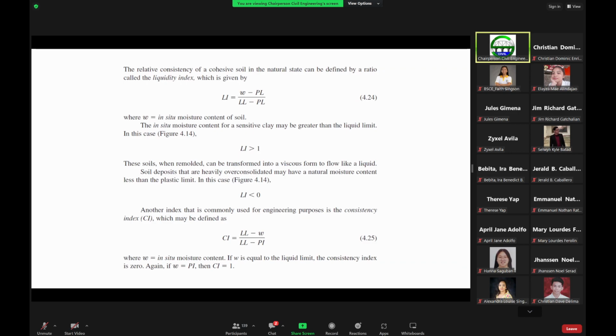So depending on where the soil is located, above or below the groundwater level, normally we have collapsible soils and expansive soils above the groundwater level, while we have problematic soils such as liquefiable soils and compressible soils below the groundwater level.